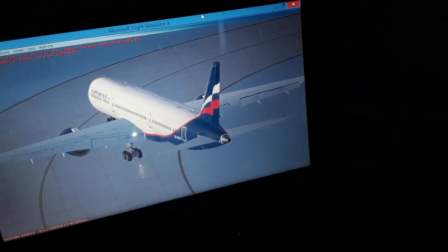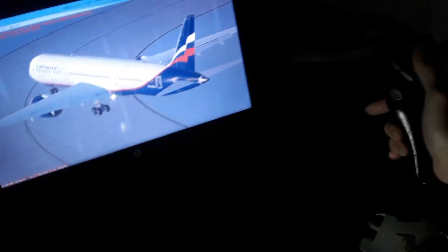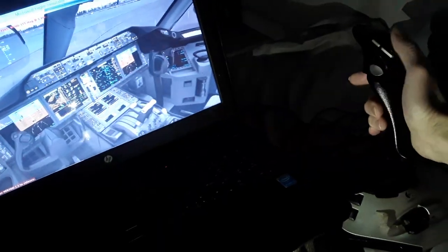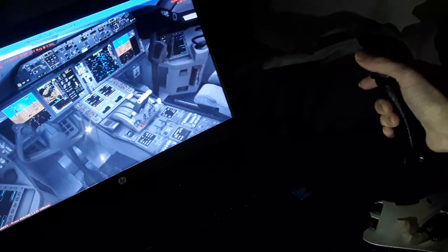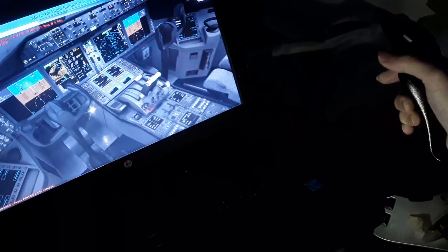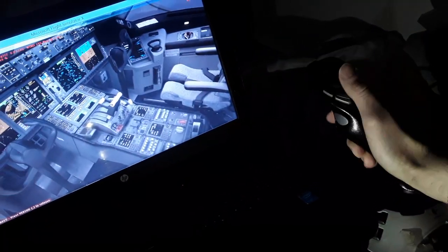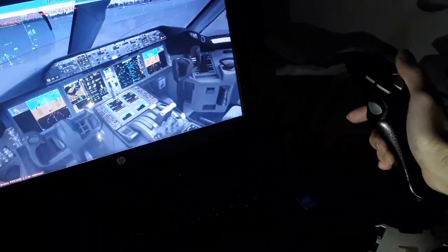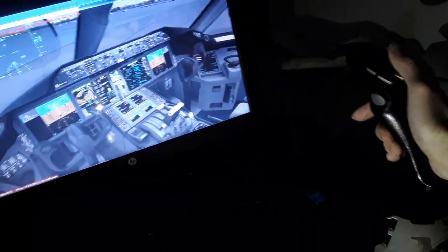It changes the aerodynamic lift like this and you make turns very easily. The longitudinal axis is the roll axis of the aircraft. So you use the side stick left and right in the Airbus aircraft. You use the control wheel of your yoke in the Boeing aircraft to make left and right turns or balance the aircraft in flight. Very easy, simple principles. Climb and descent, make turns left and right.